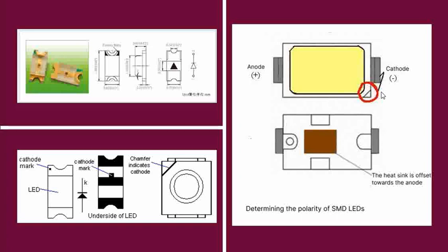So overall, the diodes are the easiest ones to identify, and the capacitors are a little confusing, based on the different electrolytic, tantalum, axial, and through-hole polarity markings, which differ within the same capacitor family. These are some of them. We will discuss more polarities, common mistakes observed in schematics, and common problems seen in designs in upcoming videos. Thank you.